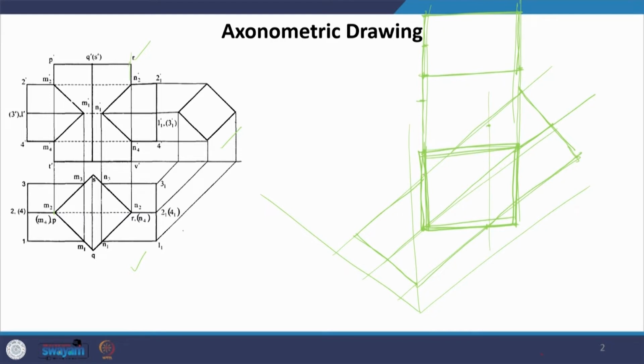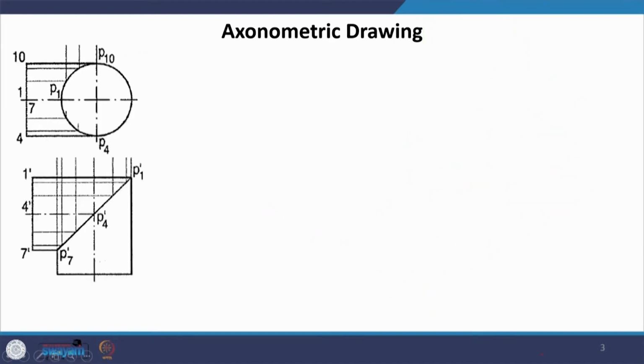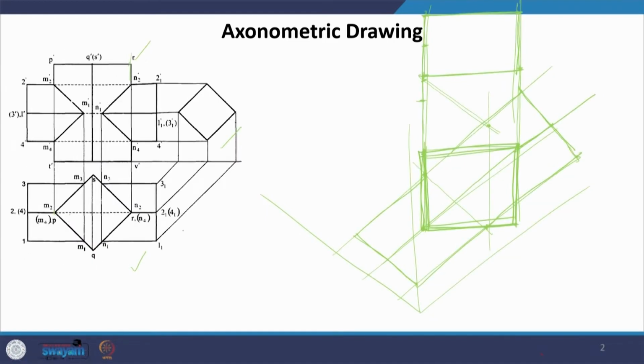There is another point which is M3 which is here, again it is coming on the same line because this is inclined at 45 degrees. So, we will see this M3 coming at the same height as this, but since it is slightly behind, and if you see this, you can join this as a line, and when you look at these will also be joining in a parallel line like this. So, this is where the other point is going to be, and then we have the fourth point which is going to come below this, which is M4, which is again below this.